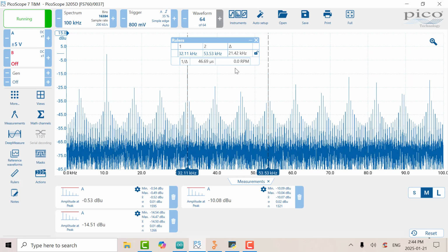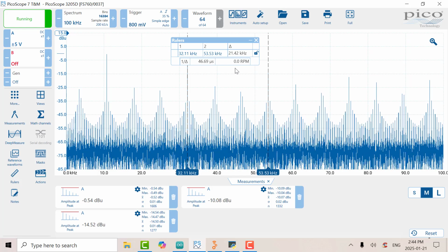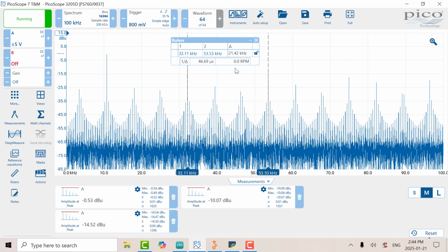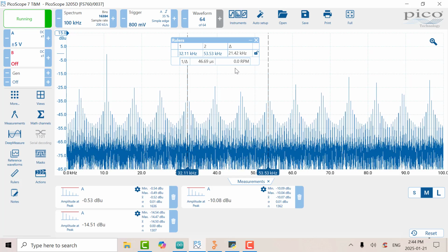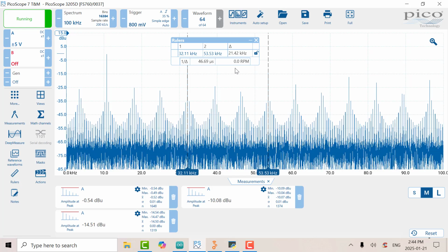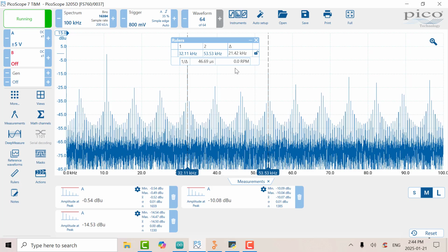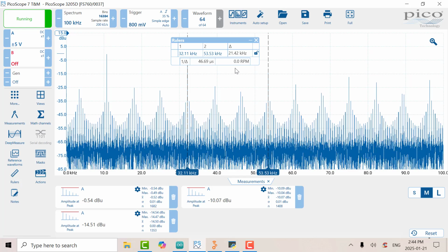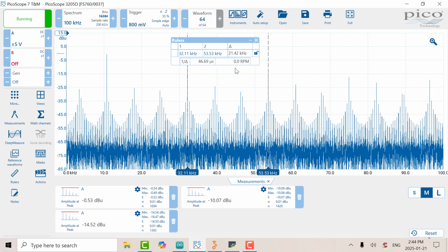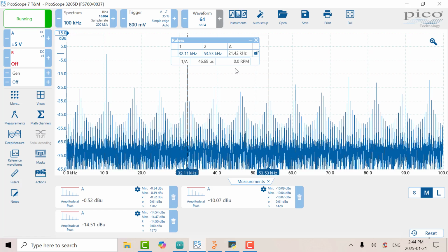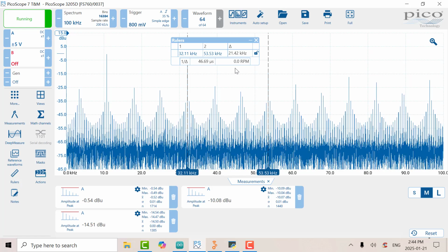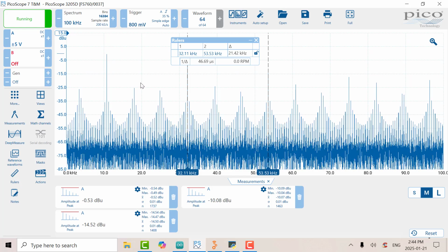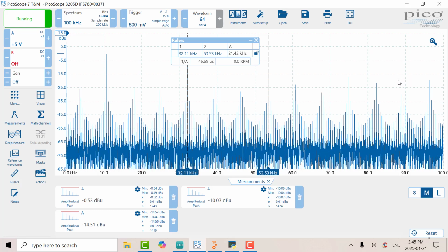The reason we're looking at the square wave is that traditionally when you had a VFO in amateur radio, you would use some form of a tube or a transistor or an FET or an NPN with an LC feedback, adjustable L or adjustable C, and that would give you a sine wave output. But if you're going to use the clock chip in that type of a mode as a modulator or a demodulator, then you have to consider the fact that the square wave does have the component you want, which is the primary component, but it does have all the other odd components as well.